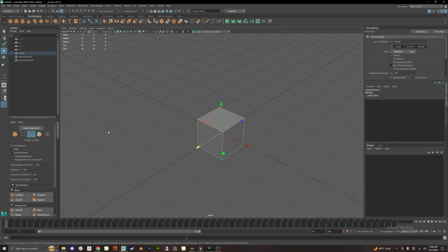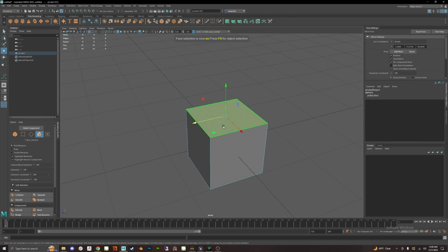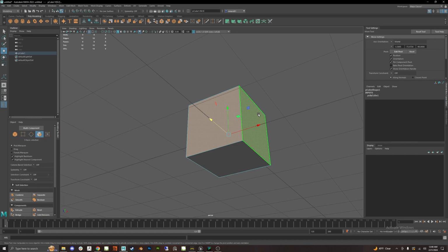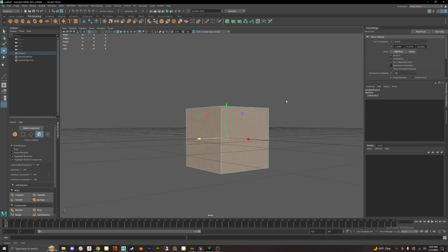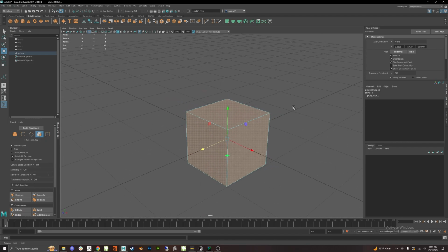Now, something you need to be mindful of when you're doing this: we started with this face, obviously right here. If I went into F10 mode and now I have all of the edges, and I hit Control F9, that's all of my vertices. But if I went back to Control F10, you see it selected all of the ones below it now. And if I went into F11, it's slowly growing the selection, because it's selecting more than what was originally selected. So that's just something to watch for when you start doing this.